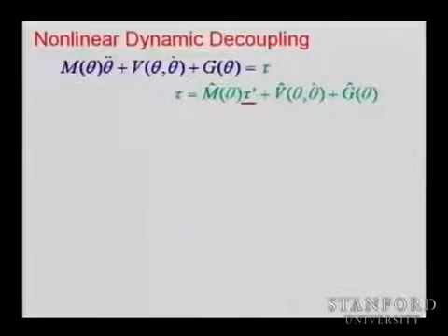So think about just taking a controller that compensates for the gravity estimate. Essentially, if this is perfect, I take this out, so this is not anymore in the equation, right? If this estimate is perfectly equal to this, this will drop. Your controller will be m acceleration equal m hat torque prime.